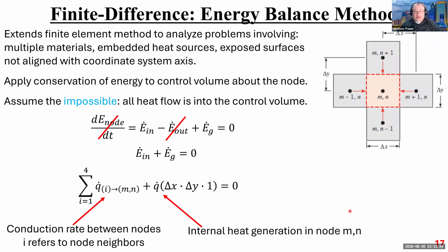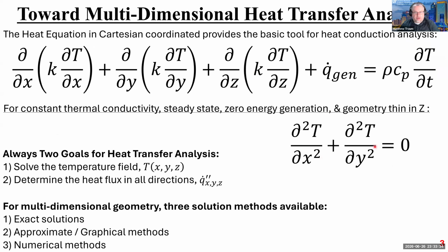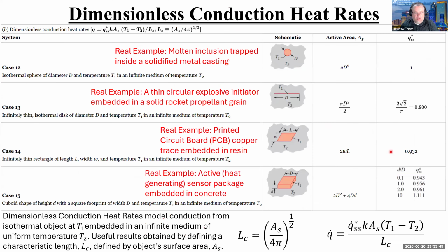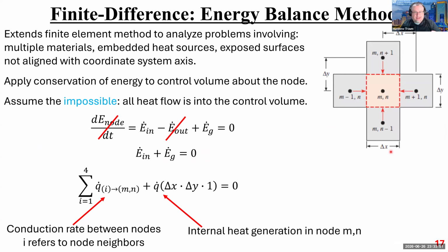Okay, so this can now get a little bit more complicated. Whereas before, when we were solving this, remember we said that heat generation had to be 0 to get us the exact solution to Poisson's equation. Well, now we can get a little bit more complicated because we're no longer solving these complex, horrible differential equations. We're now just summing up averages. So if I had a node that had its own internal heat generation, I can add that, and I can actually solve for that heat generation.